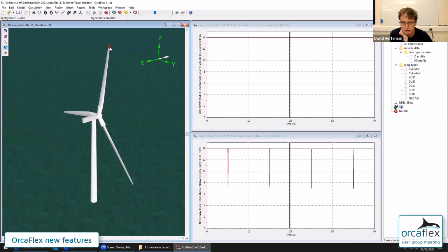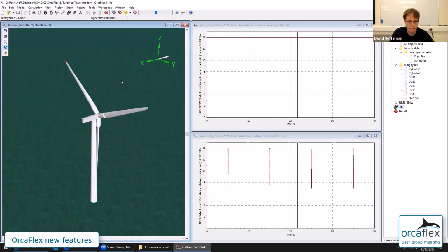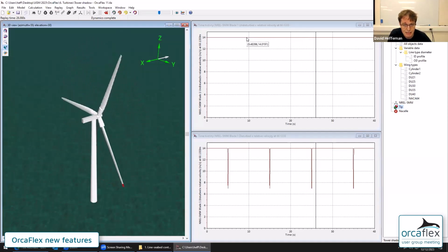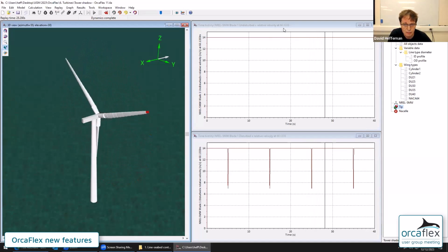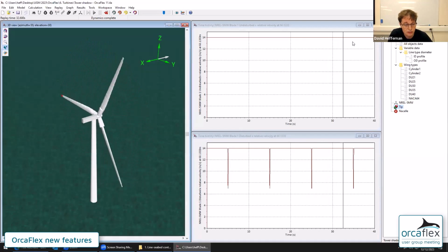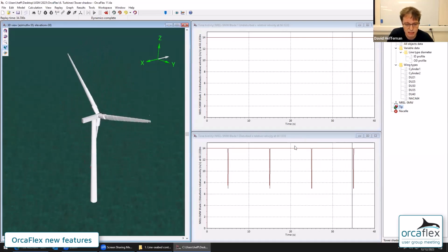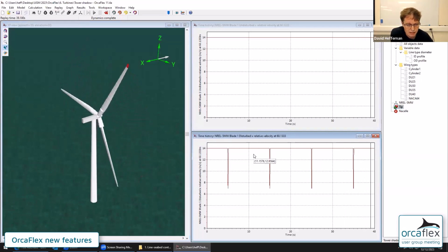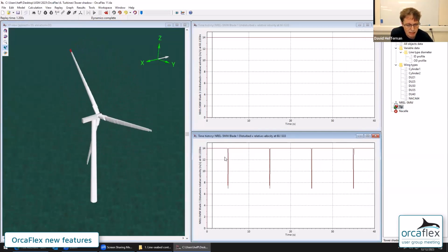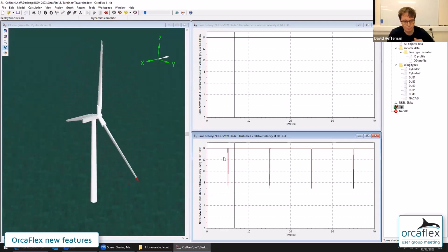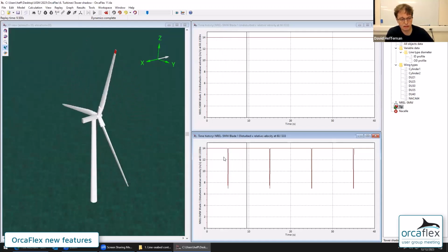And it's really just a visual indicator, so you can see when the replay is running 2 graphs: undisturbed relative velocity at that same point on the blade, the NB of blade 1, at the top. So it's just a constant wind speed in this particular model. However, the disturbed relative velocity, where the tower shadow comes into play, we see when the blade passes behind the tower, the wind velocity drops because of the presence of the tower.